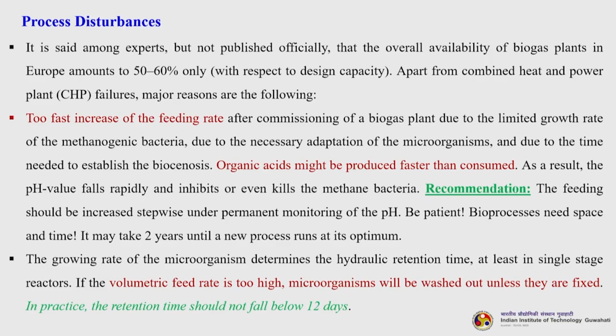The growth rate of the microorganism determines the hydraulic retention time, at least in single stage reactors. So, if the volumetric feed rate is too high, microorganisms will be washed out unless they are fixed. In practice, the retention time should not fall below 12 days, the minimum retention time.